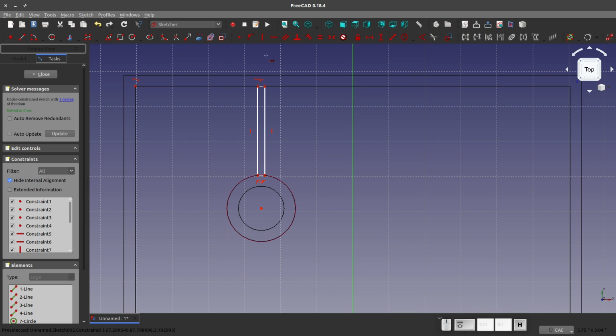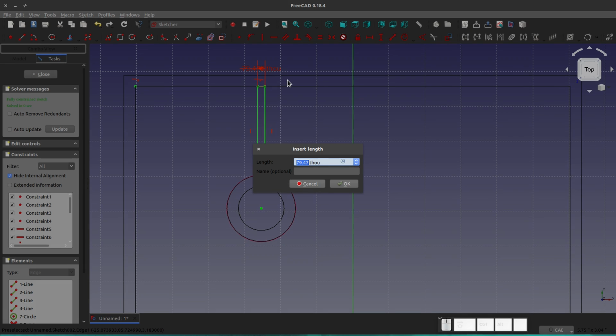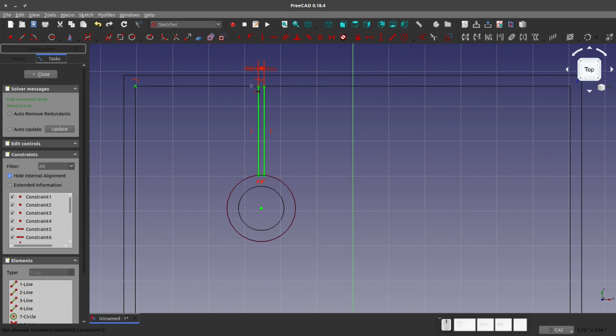So I'm going to give this the max thickness, assuming I'm working with a semi-crystalline, of 0.125 inches. We'll get rid of thou. And we're going to say times 0.5. Right? So that's half my wall thickness. And let's do the same thing over here.